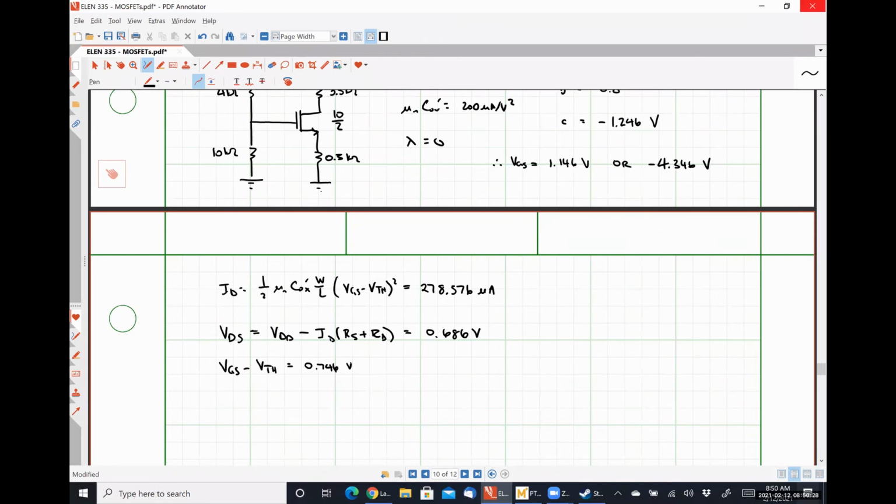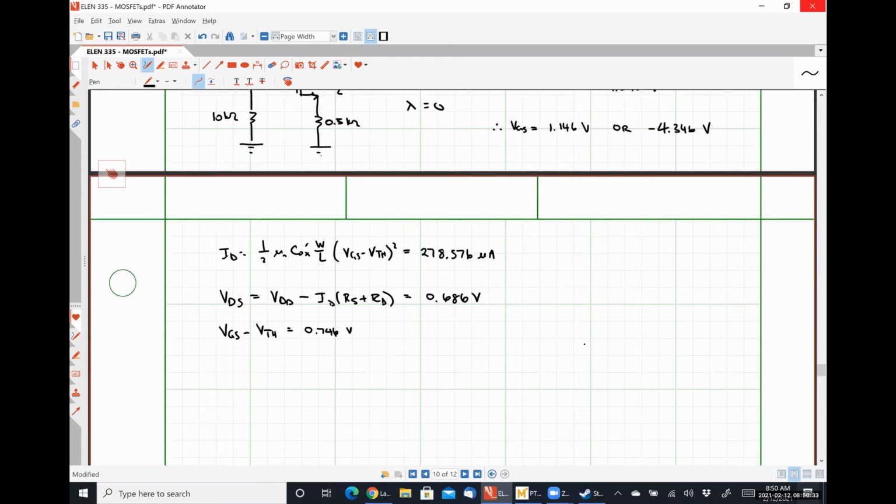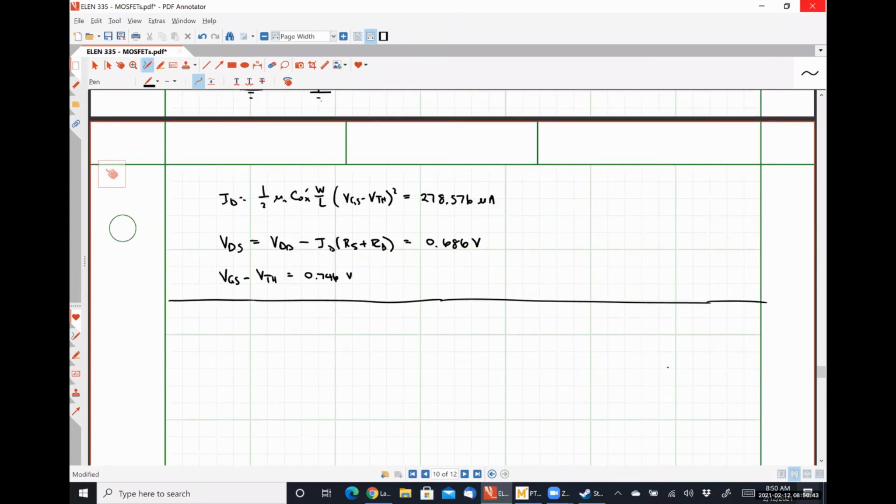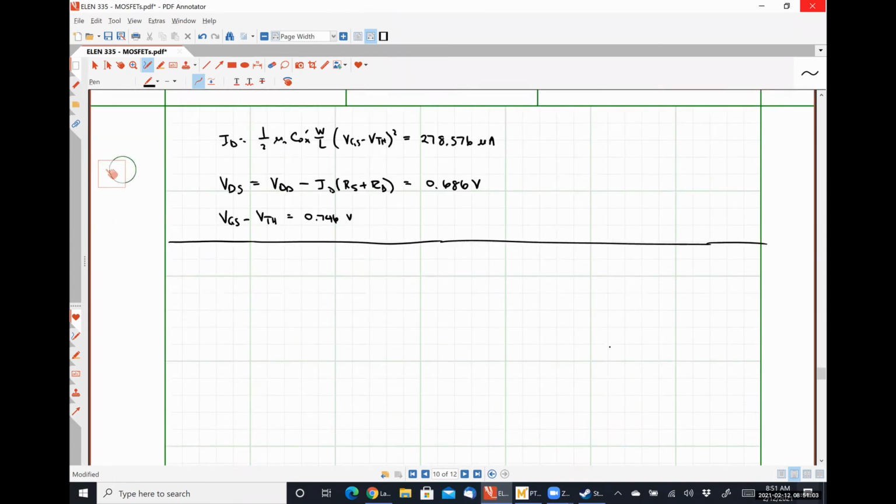Now, here I'm going to show you guys the math involved with going through and figuring out our fundamental equations for triode operation. All right, we're going to come back to this guy in a second. So this is where I said we can tell what VD, VG, and VS are very easily, much more so than we could determine what our terminal voltages were for a BJT circuit, but this is where it's significantly harder than a BJT circuit.